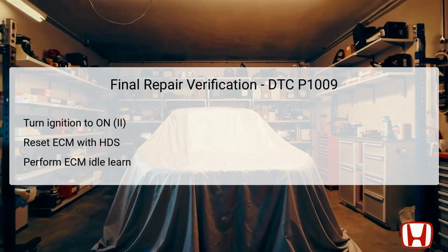Start by turning the ignition switch to the on position, thus powering up the engine control module, ECM. Use the HDS to reset the ECM, which erases any old learned characteristics and allows it to recalibrate based on the changes made. Next, perform the ECM idle learn procedure. This step is vital for the ECM to adjust to new operating conditions accurately.